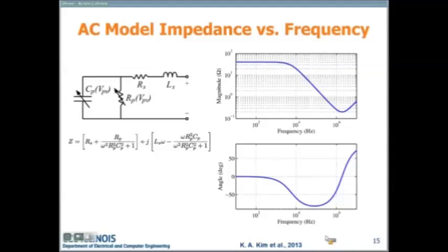One really good point you bring up is the irradiance change. A lot of people just assume it's constant, but it does change, especially here where it's cloudy and windy, the irradiance can go up and down. I think, Raj, you've looked at some of that data too. It can change very quickly. So in general, we haven't done enough analysis on quick transients and how much that can affect the stability loop or other things like that.